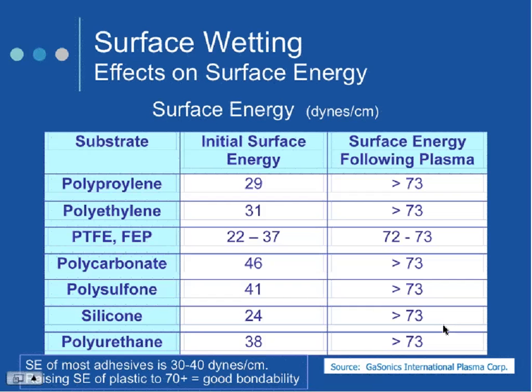Does anybody use plasma treatment or corona discharge? You have? It's effective, right? Do you use it just on the low surface energy materials? No, it's all over. The trouble is it's time dependent. That's the problem. Yes, it is. Yes, it works as a good cleaner as well as raising the surface energy. And some people use it just for cleaning the surface.